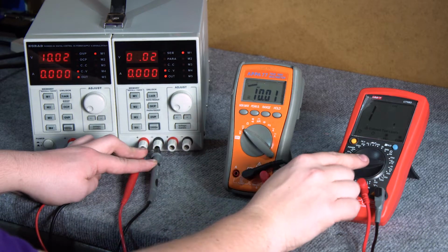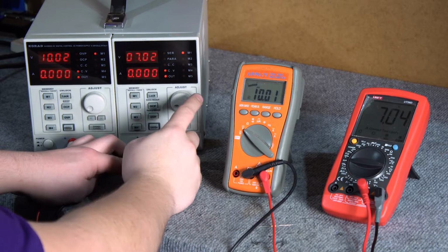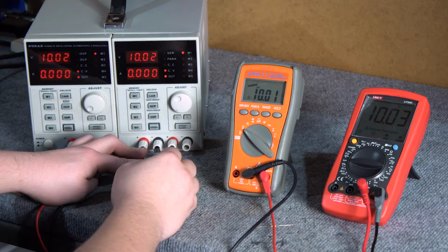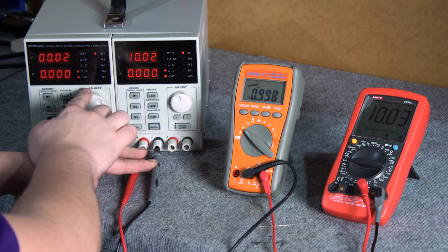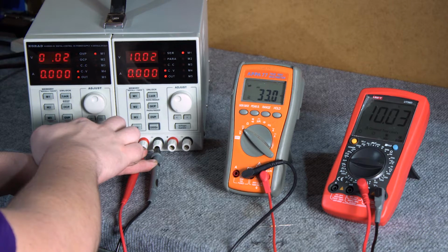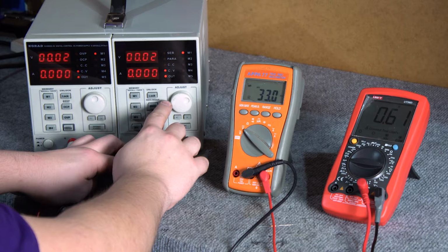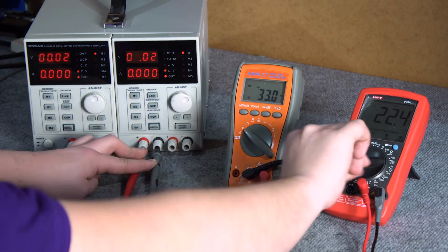It is worth adding that the lowest range, often 200 millivolts, 400 millivolts, etc., is the most accurate and the least protected, so be careful when you want to measure very small and high voltages. The second meter automatically selects the range. This function is called auto range, so we do not have to wonder if we have chosen it optimally to get the most accurate value possible.